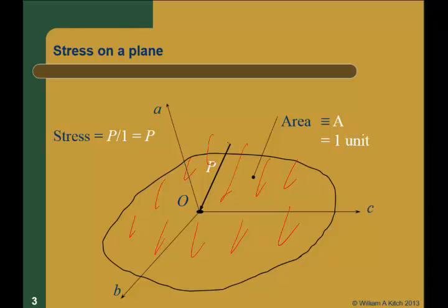And then when we do that, it'd be useful to resolve this stress into its components in those 3 directions. Well, I shouldn't call them principal directions. We don't know that yet, but those 3 directions. So the first thing we're going to do is separate that vector into its normal component to the plane and that part that is parallel to the plane. And that normal component we're going to call the normal stress.